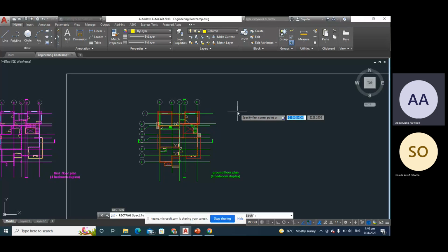You can't say that because your architect has sized one area for you to place your column, you now have to utilize the whole thing. It's not economical. You understand my point? So it's always good to optimize our design. It's part of design optimization. So you ensure that you have used your structural elements to the expected capacity, to avoid over-designing. Over-designing is doing a very expensive design, a design that is not economical.